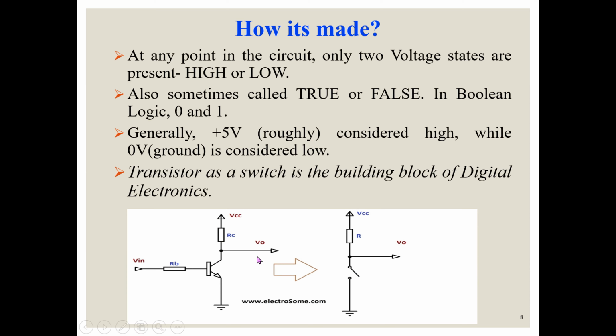These are two different kinds of transistors where a load is given. One of the transistors is connected, and here a resistor is connected to the base of this transistor. The input signal is given to the resistor, and from the resistor it is given to the base of the transistor. This is the emitter and collector of a transistor. And here it is VCC, a high voltage, and this is the ground terminal, which is called 0 volts.